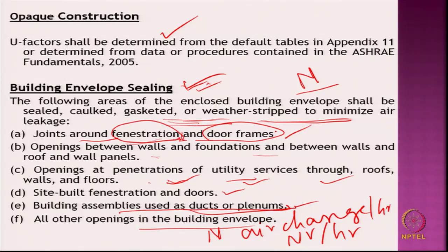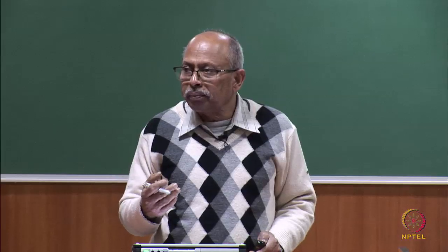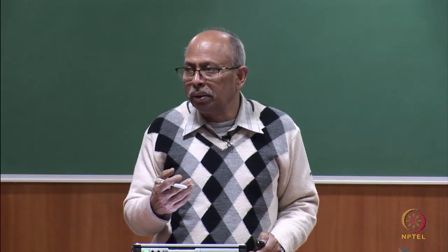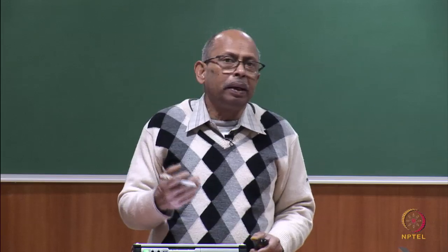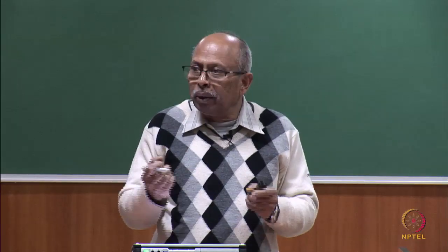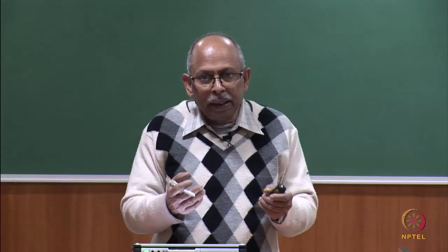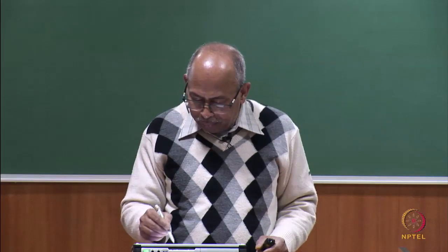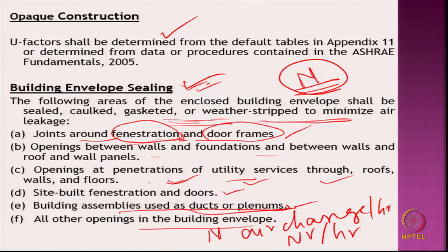That is basically, you do not want this to be high, because if the infiltration rate is high, and the outside air is warm, it will bring in heat together with it, right. And if it is a cold climate, then it will take away the supplied heat from the room to outside. So, therefore, you do not want this to occur by default.